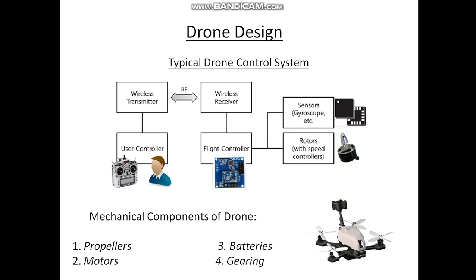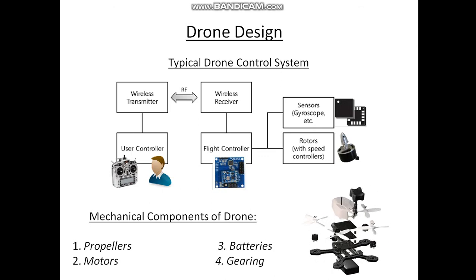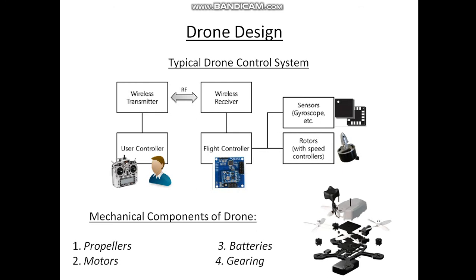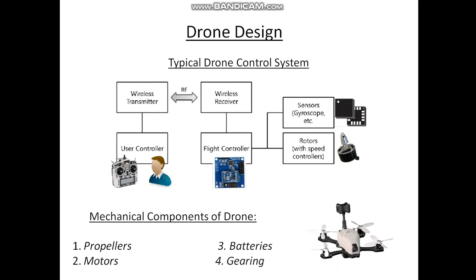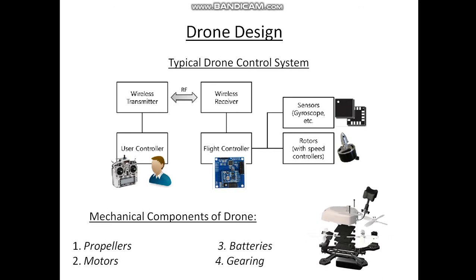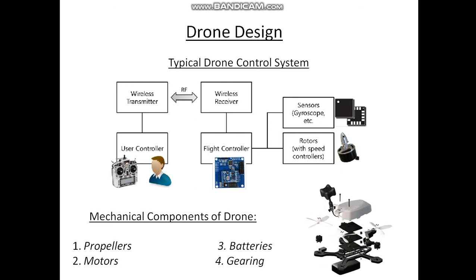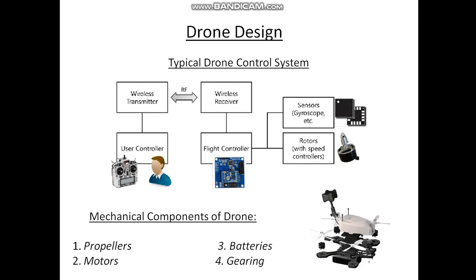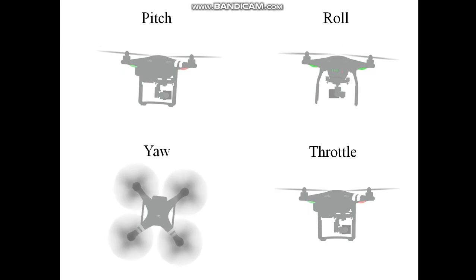The propellers. They play a key role in providing fully attached flow to the drone and maintain the drag to thrust ratio in the ideal range. For motors, the principal concern in selection is power output versus motor weight, as any weight added would require power expenditure to keep it aloft. For batteries, in addition to the weight benefits, the batteries should be homogeneous in performance, providing consistent and reliable performance at lower cost. Some drones also use gearing to provide desired reduction ratio.